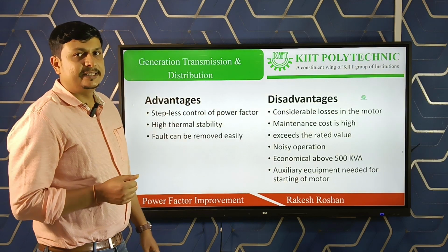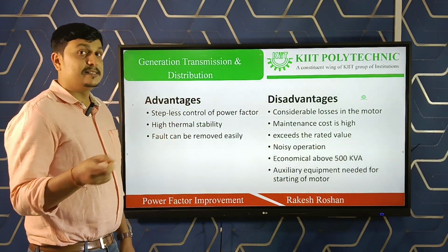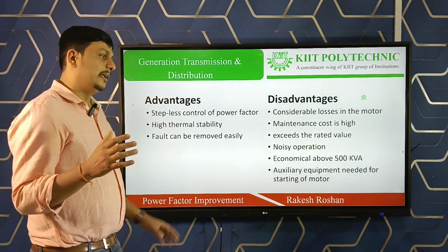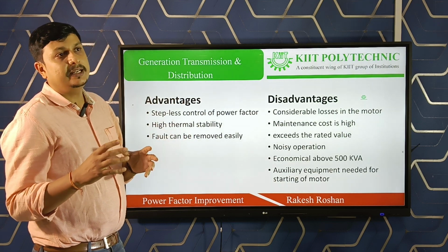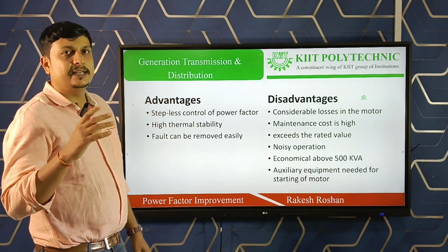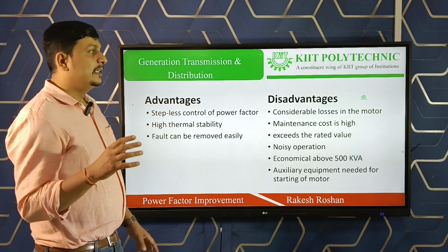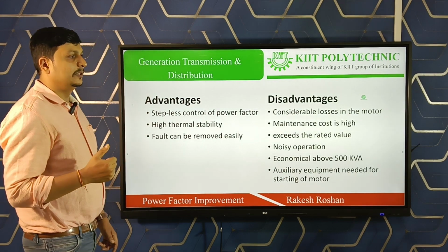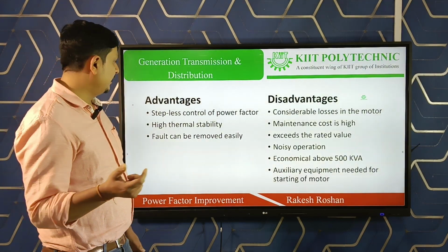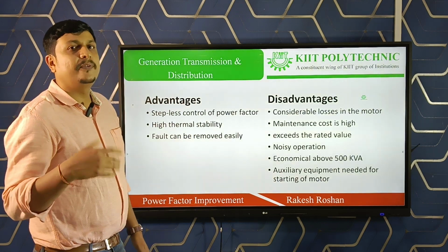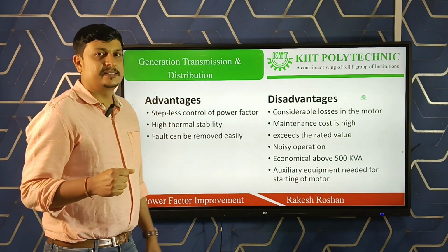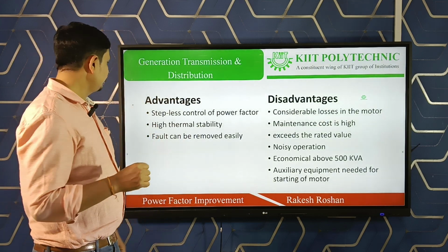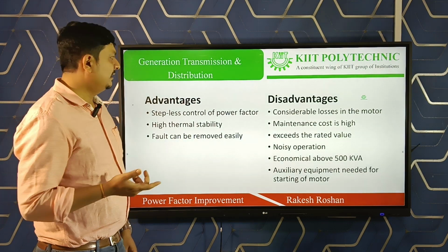So there are some advantages of the synchronous condenser. As I said in the earlier slide, it can be operated at any power factor. In the static capacitor, we connect and disconnect capacitors in steps, but a stepless control is available in this type of power factor improvement equipment, the synchronous condenser. That makes it more flexible. It has high thermal stability, and it can also withstand larger values of short circuit current. Faults can be removed easily.